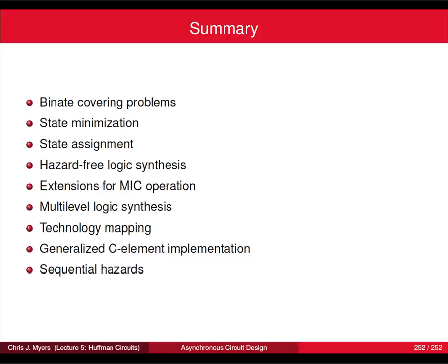So one possibility would be to do logic synthesis, for example. You start with a burst mode state machine, and it's already had state assignment done to it, and you could do logic synthesis for that, hazard-free logic synthesis. Other options would be doing things like adding the state variables to a burst mode state machine. And I have a number of example files I could give you. So if you wanted to do the state assignment part of it. I'm not sure about state minimization, whether that's really interesting for burst mode machines per se. I would think it would probably be state assignment or logic synthesis, or it could be generalized C-element logic synthesis.